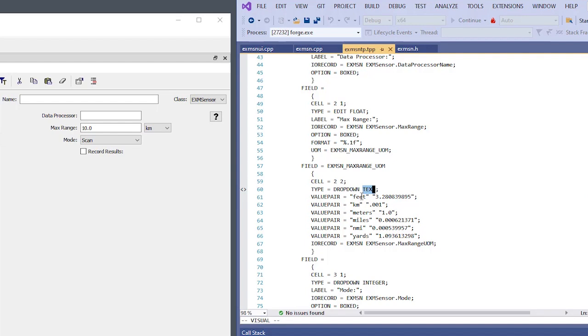And it has to have values. The first value is the value displayed on the user interface, and the second value is a conversion factor. The conversion factor for the base unit of measure, and you choose what you want the default base unit of measure to be for your value right there, is always 1.0. And these other values are the multiplier that you would place on values in meters in order to convert to miles. So this is the value to convert meters to kilometers. This is the value to convert meters to feet.